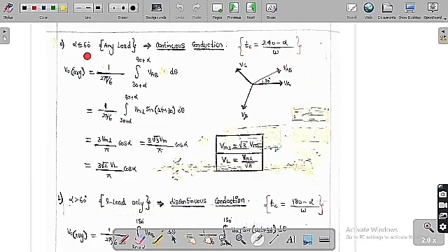Now I have already told you that for alpha less than or equal to 60 degrees, for any load, continuous conduction is always possible. Therefore, if you want to find the circuit turn-off time, meaning the time for which a thyristor is going to face the reverse or negative voltage, it is 240 minus alpha by omega. For this much time the thyristors face a reverse voltage, because each thyristor conducts for only 120 degrees. So 360 minus 120 is 240.